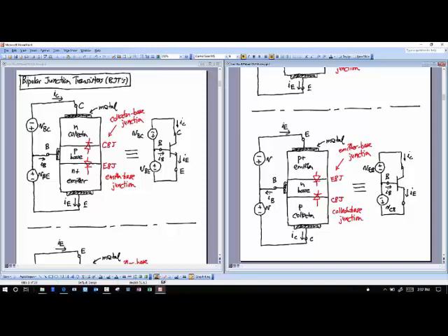And what else? Yes, this will now be the emitter. This will now be the collector. And the arrow for a PNP device, and this is how you tell the difference on a circuit diagram between NPN and PNP, the arrow is going down in that direction, okay, from the top. Okay, so this is now a PNP device. You can sort of compare and contrast what you have on both sides there. They look the same, it's just you replace the P's and the N's in both of these devices. Okay, so that's device structure.